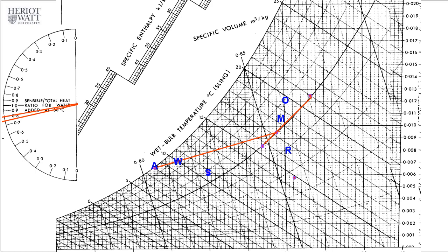So that is the room ratio line for one zone, and this is for another. Therefore, from W after the coil to any point on these two room ratio lines, the easiest way is to reheat. So we draw this reheating from W to meet the two RRL lines, the red lines. And these two points show the supply temperature for the two zones.